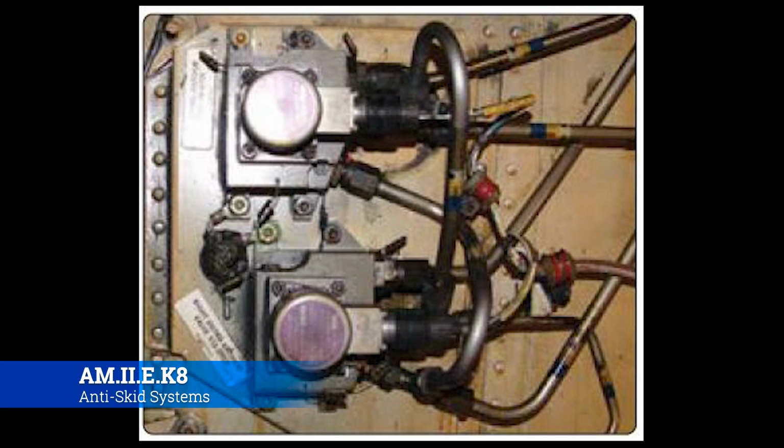They actually move. The LRU, I have seen anti-skid system LRUs go bad. It's definitely not super normal, but it does happen just like any other LRU out there. So these you don't really have to worry about as much. The wheel sensors typically are going to be the bad thing, and the auto test, the BITE test on the box, will usually tell you what that is. On a 737 MAX, however, maintenance data pages will also tell you that as well.